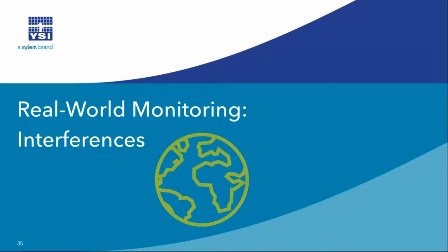Once the sensors are calibrated, if you have stored them properly and taken care of them, kept them clean, they should be fine. What I do often recommend before people go out to the field with their ProDSS is do a quick cal check. Dunk it in some water, make sure it's still looking at 0, and you should be fine. And you'll be able to tell also by how those QC scores look.